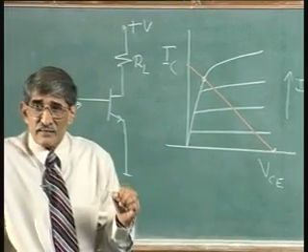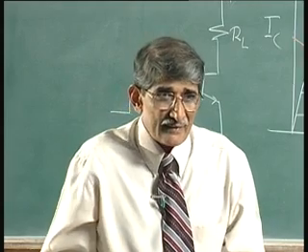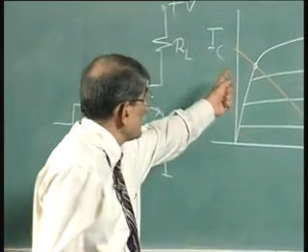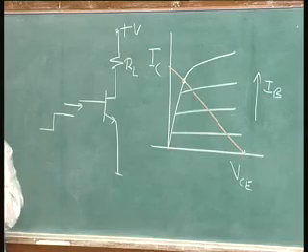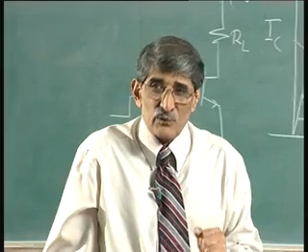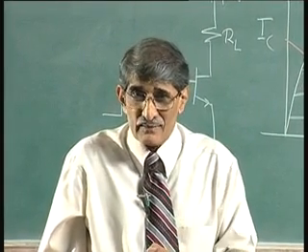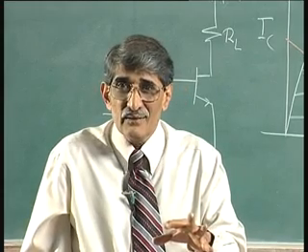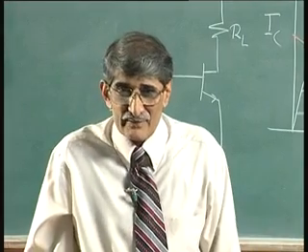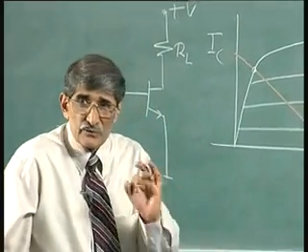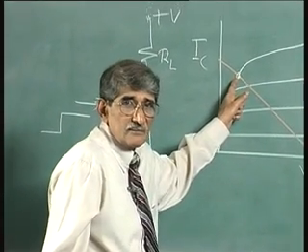When the transistor goes into saturation, you know that there are charges stored in the base region, collector region, everywhere. So, if you want to come back from here and turn it off, the charges stored in the various regions of the transistor will have to be removed. That is what makes it slower. If you want to prevent the transistor from going into saturation, what is done in the TTL is, I am showing one inverter only, some portion of the TTL. You will have another resistor here, that is a different story, but I am showing finally the principle.